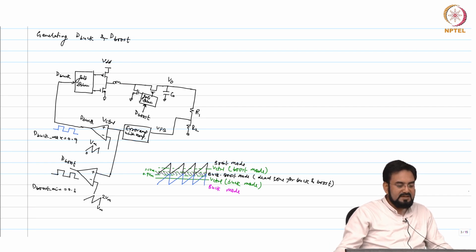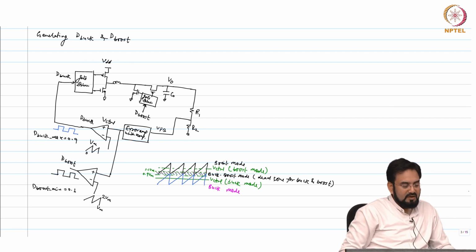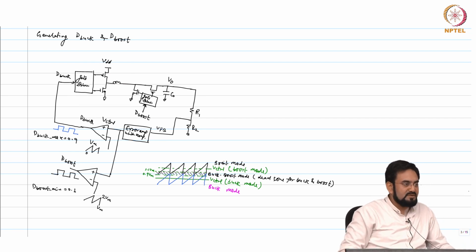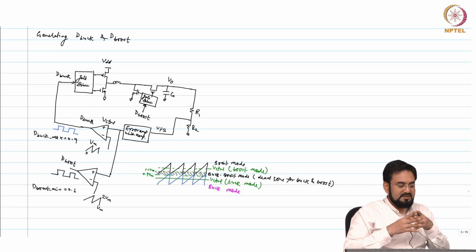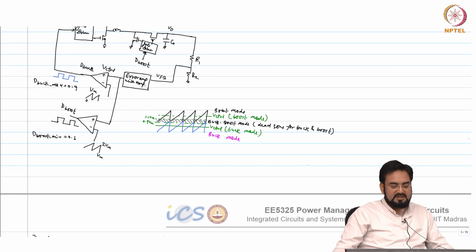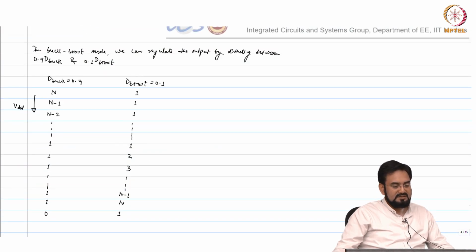You can use a 3-bit or 4-bit ADC. You can do a flash, or you can have an accumulator, but the accumulator will be slower. If you do it with the flash, then it will be faster. So that's the difference. Depending upon how much resolution you require, you can choose whether you require a 3-bit or 4-bit. If you require 4-bit, then you will get 15 different codes.